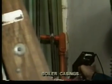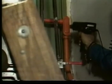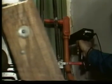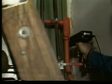Boiler casings are tested using the Ultraprobe scanning module in the fixed band. Scan the casing itself at a set distance. Listen. Sometimes you may need to use the rubber probe. Adjust for background noise which may interfere.